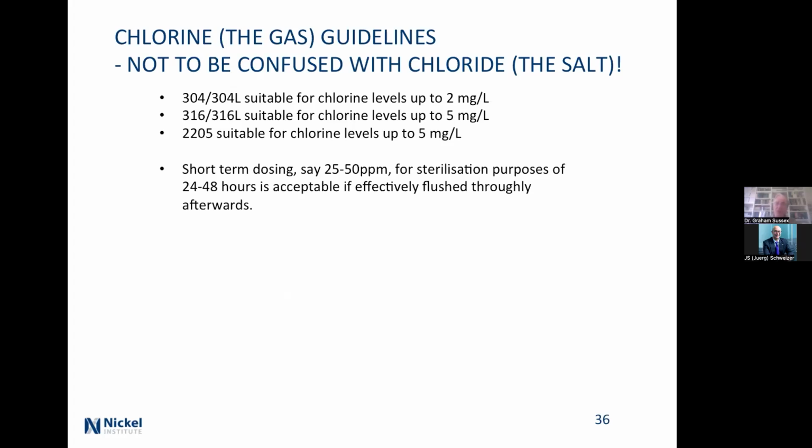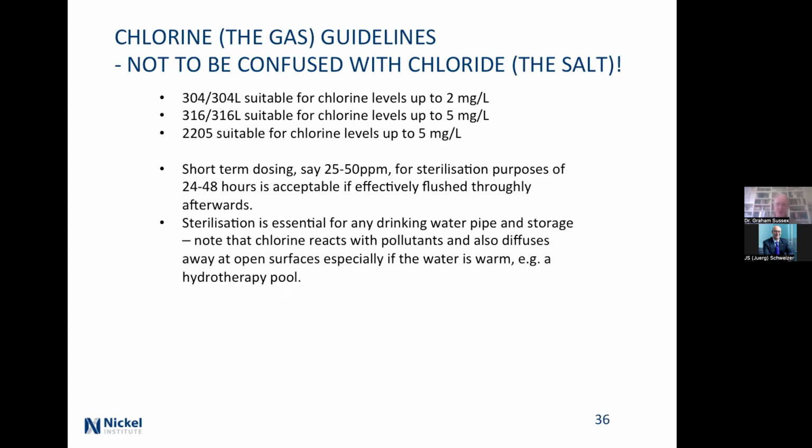One of the things that you sometimes see in hospitals is people wiping down surfaces with a rag with hypochlorite on it, and then they don't rinse it. And so you wind up with a rust line or a rust scrape across the surface where the chlorine was left. If you're talking about drinking water, it's got to be sterilised. Note that the chlorine is going to react with pollutants. So if you've got water that's got lots of pollutants in it, you have to worry about what it's going to be at the end. And that's why people monitor the level.